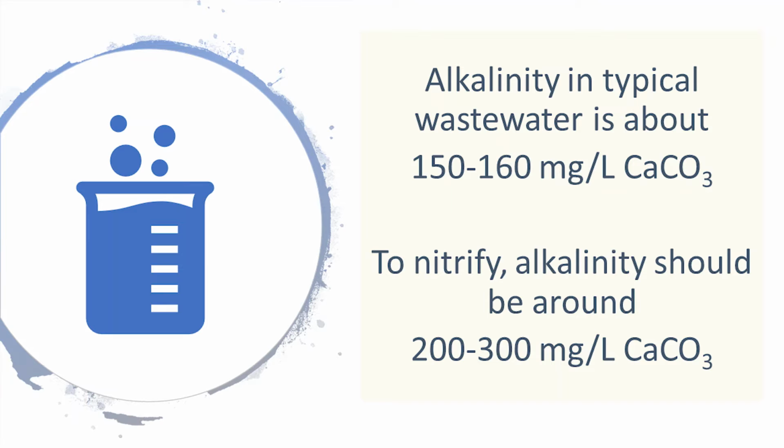So alkalinity is really key, and we have alkalinities around here in our wastewater somewhere around 150 to 160. What we really need to nitrify much of the wastewater should be up around 200 to 300. For instance, in Florida or other parts of the country, typical wastewaters run in the 400s, and that's plenty to nitrify all of the ammonia.